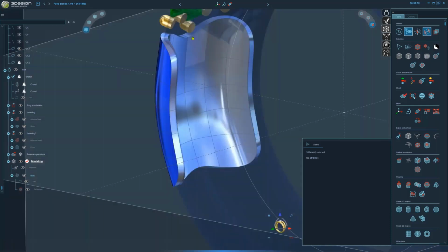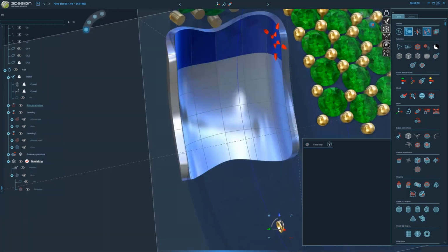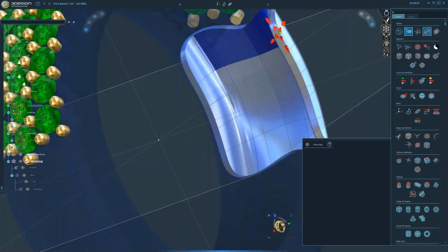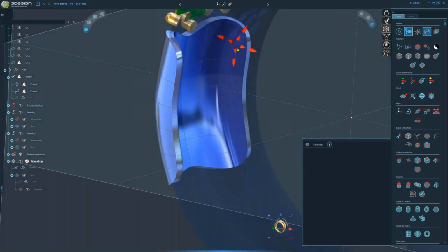Now I want to make sure that this piece is inside my ring. Right now, that inner surface is basically matching the surface that I drew it on since we use retopology. So I'm going to select the entire back faces. To do that, I'm going to select one corner, use my face loop tool. That way I can quickly select these faces here, and then I could do the entire row down. That way I don't have to control click each one of those. So that's your face loop selection. Very helpful when you're selecting a whole pattern or group of faces.